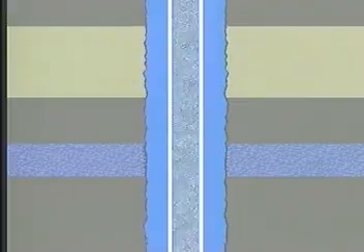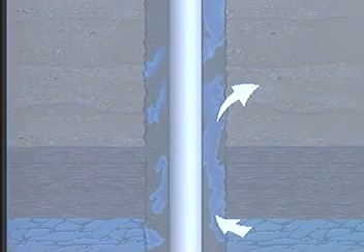Friction reducers are added to permit the cement slurry to enter a state of turbulent flow at lower pumping rates and therefore at lower pumping pressures. This reduces equipment wear and horsepower requirements, as well as avoiding formation breakdown pressures. Turbulent flow is important to help promote complete mud displacement ahead of the cement, preventing the channeling of mud, which can lead to behind-pipe pressure communication.